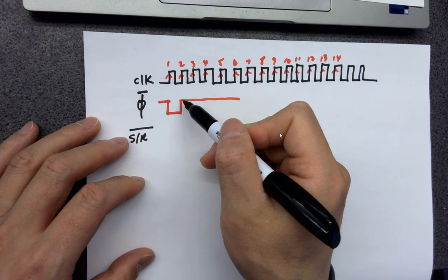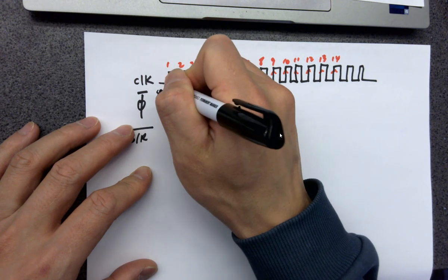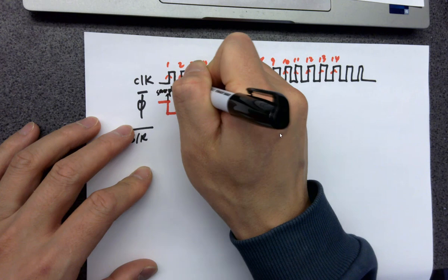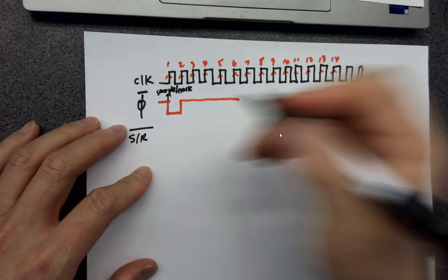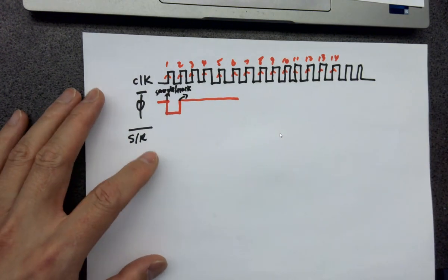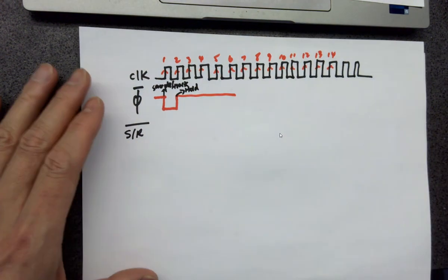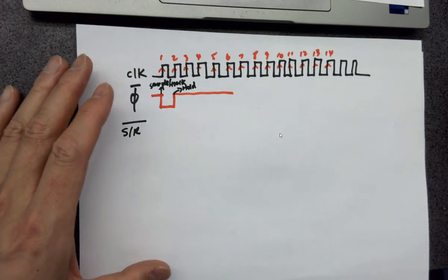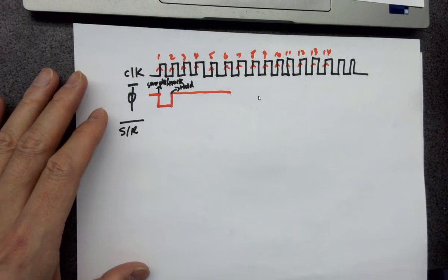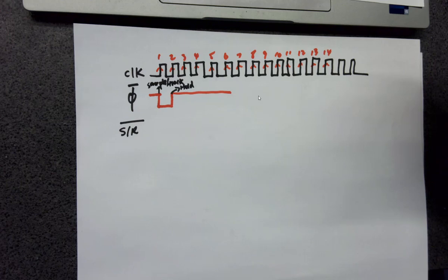There are only two options, really. Here, sample and track. What about here? Starting what? Hold. Come on, only two options. You could even just guess, right? Okay, so we start holding, which means the DC voltage is available. So the value is ready, provided to the SAR ADC. You are ready to do the conversion.